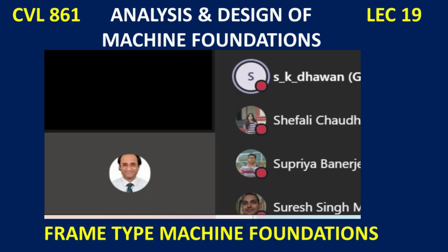But for any structure that we deal with, first of all we need to know the structural system, and then initially we need to make a design basis report. For the design basis report, we have to clearly understand from the architecture drawings the structural system and the loads that are going to be put on the structure, whether dead load, live load, wind load, or any other type of loads.